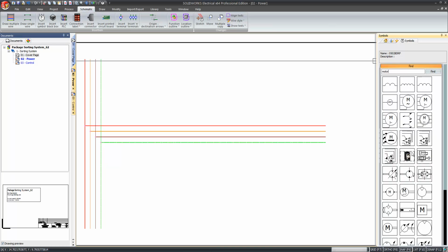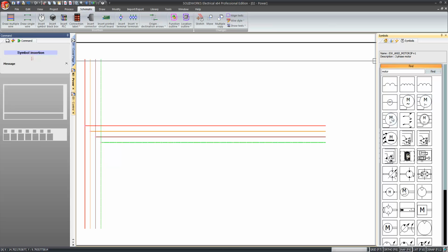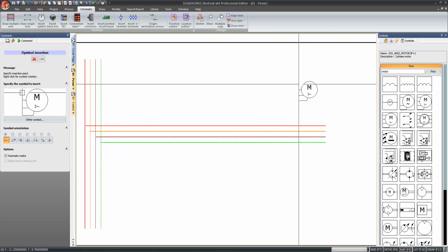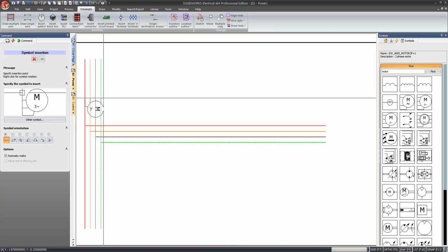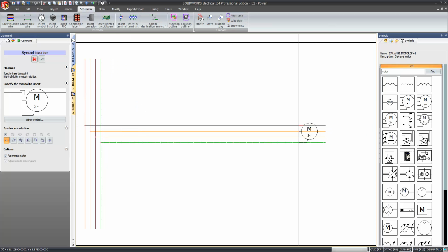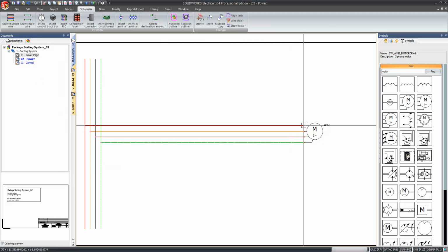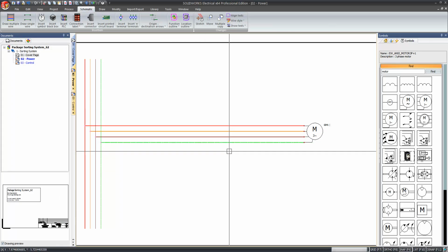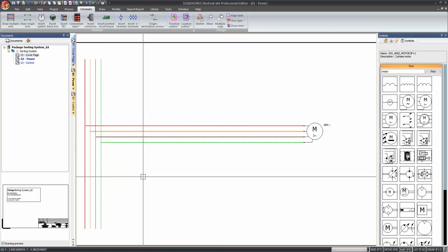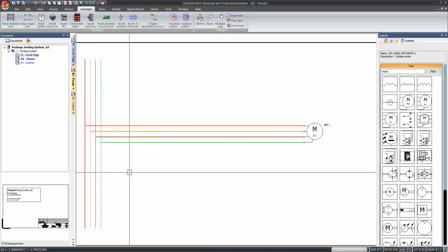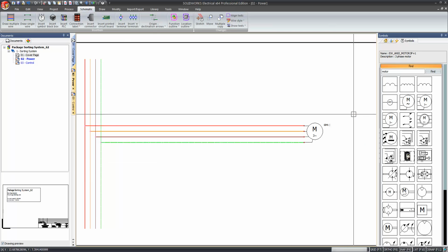So let's add a motor. If you've got two duplicate motors, because you got one maybe with the library, use the +1 version. It's one that's going to be modified from your default system library, and maybe kind of hover over some of these other wires to show how it just wants to really attach. I always make a point of putting it right on top of these wires to make it look sloppy at first, but as soon as I click the button, the wires get trimmed away. That's a big ooh-ah moment for folks who use AutoCAD LT and DraftSight and tools like that to do their electrical designs. It's amazing the little things that save people time are very impressive to them.